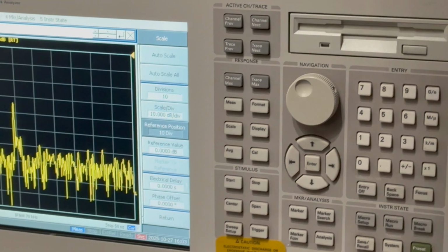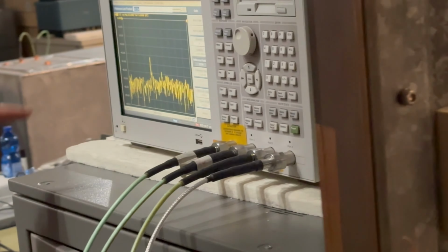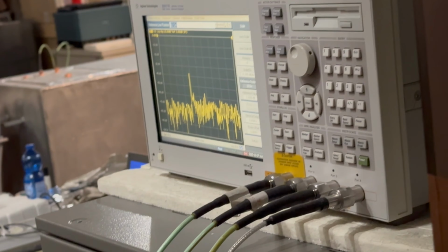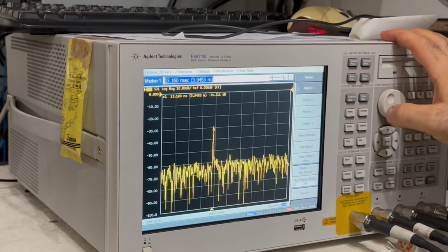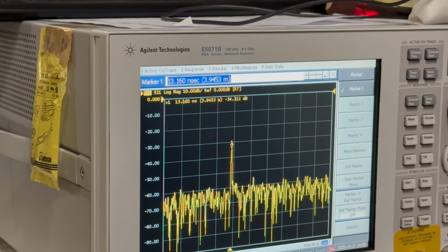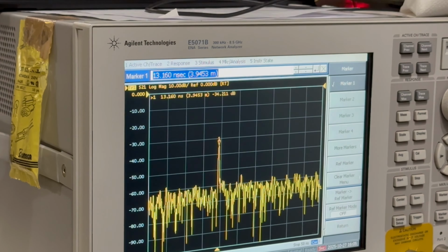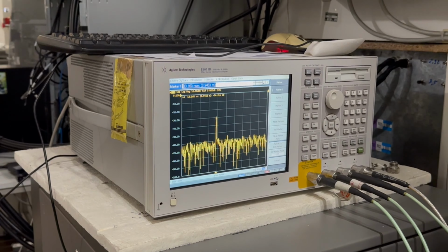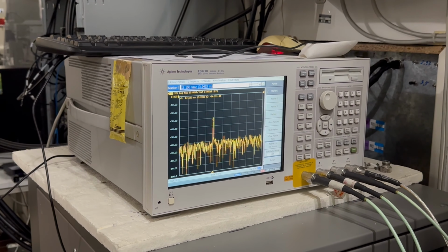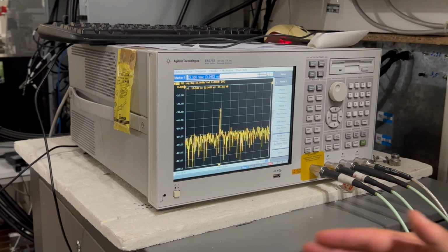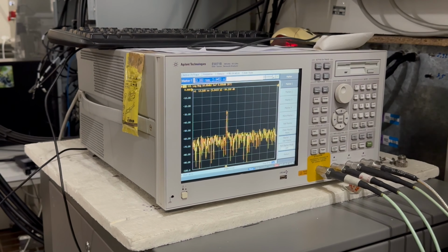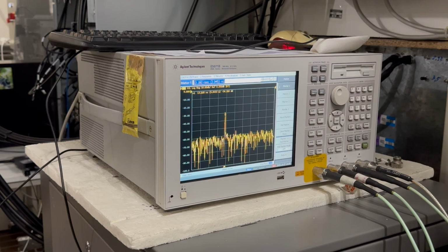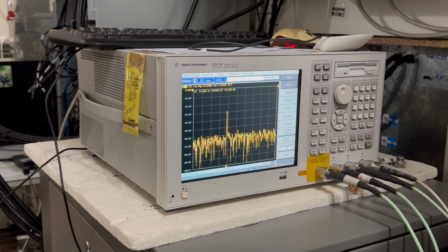Nice, probably. If I just stand there, you can see it's affected. Right, actually. Okay. So we see we can calculate the distance from the PDP, if you want to check. I also have the distance in meters, and yeah, that seems like it should be correct, the distance between the two antennas. Because we calibrate with cables, yes, we calibrate at the connector of the antenna. Yeah. Okay.